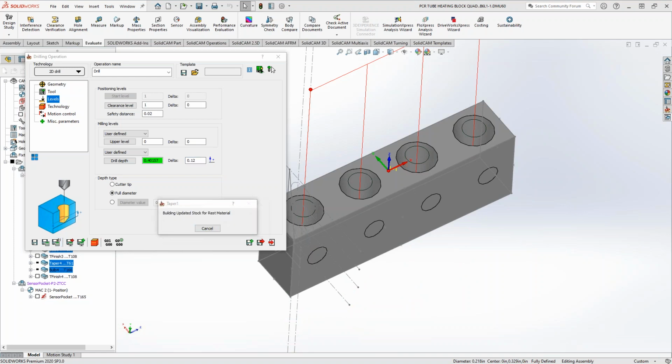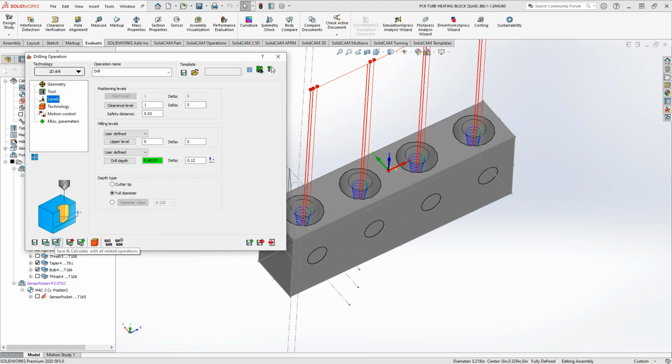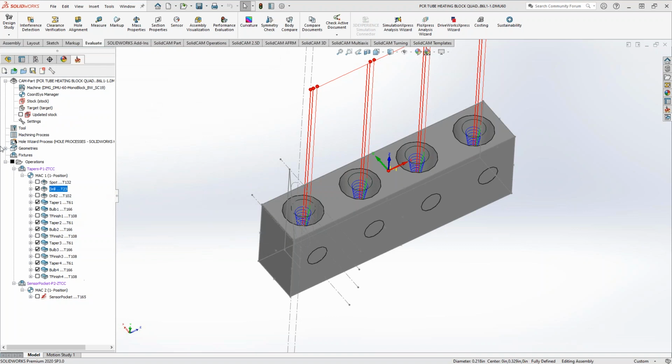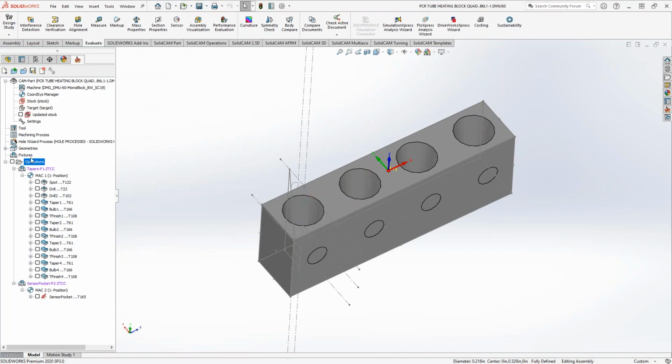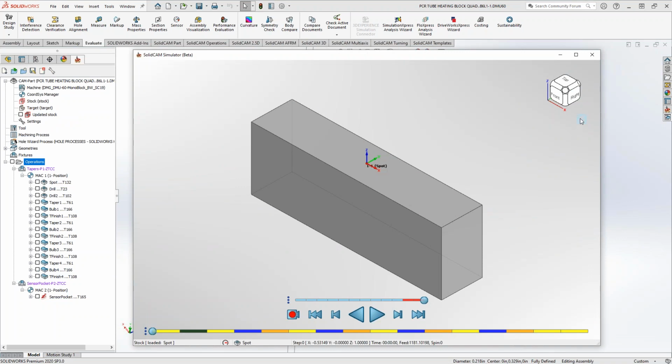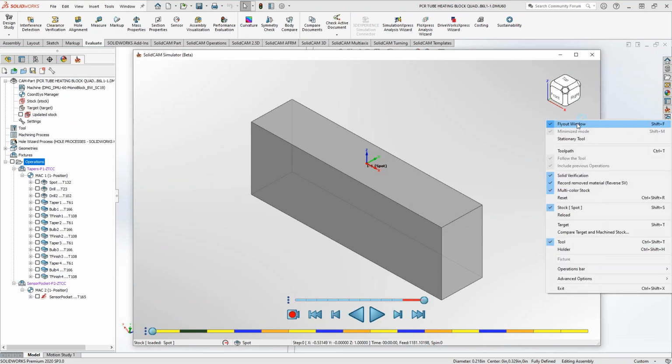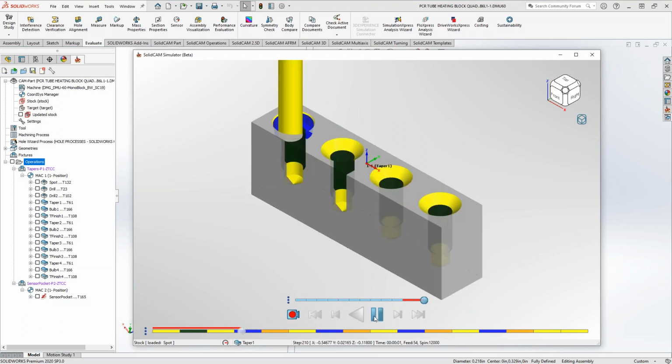And I would definitely say that the best way to approach that would be using that rainbow, just because we can see our tolerances of the gouge. So maybe in one area we're just slightly gouging, where another area we are majorly gouging into there. So yeah, if you go into the G and it shows nothing, okay, so if G shows nothing, no gouge. If it shows little slivers, you gouge something. Correct. Yes.